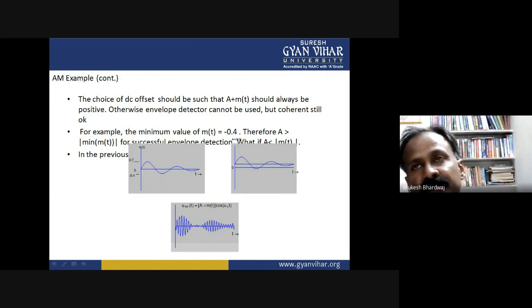For that, we know the nature of the carrier wave is sinusoidal. So the equation of the carrier can be given as c(t) equals A cos omega_c t. Here A is the maximum amplitude of the carrier wave and omega_c is the carrier frequency. Now, let us denote the modulating baseband signal with x(t). Then, according to amplitude modulation, the maximum amplitude A of the carrier has to be made proportional to the instantaneous amplitude of the modulating signal x(t).